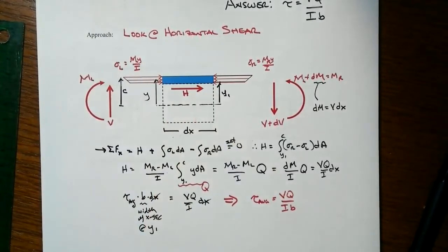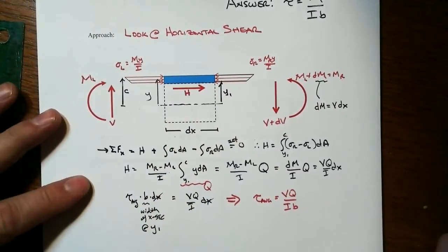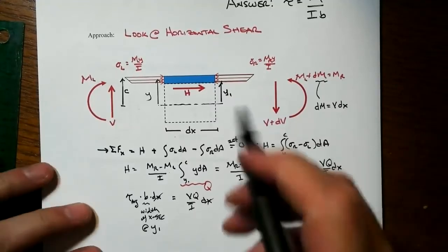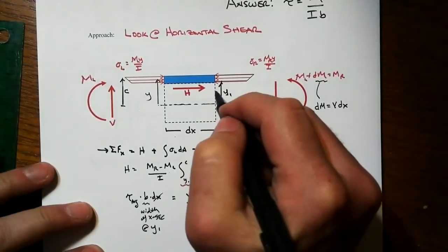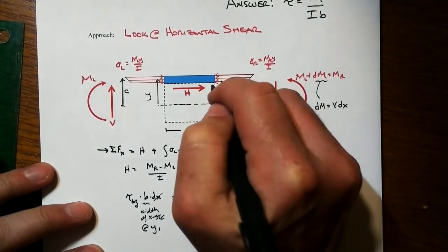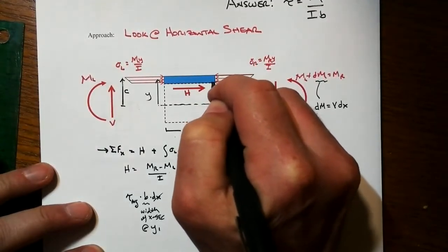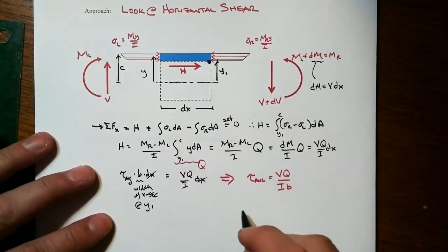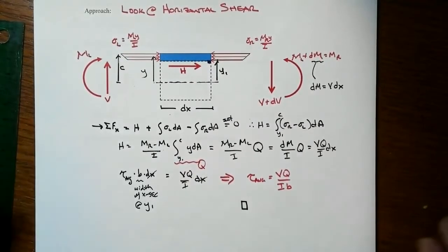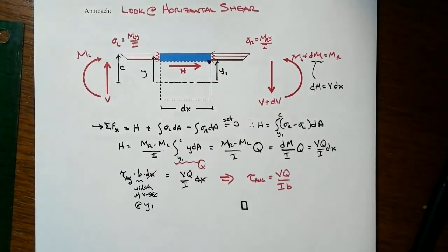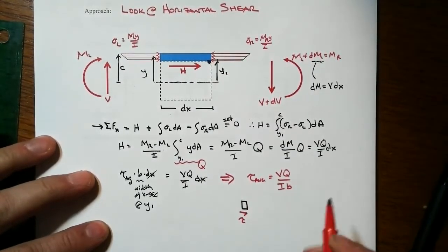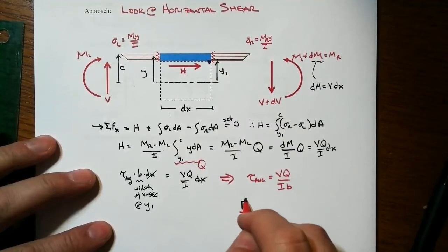Now, there's one more little piece that's kind of important here that we also need to talk about, because that's the horizontal shear stress. What does that have to do with going on vertically, right? So let's take a tiny little piece right there, right? And what we've just found out, you can do this on top or bottom, it doesn't really matter. But on the bottom here, we've got this little shear stress tau that we just learned how to calculate, right, or the model.